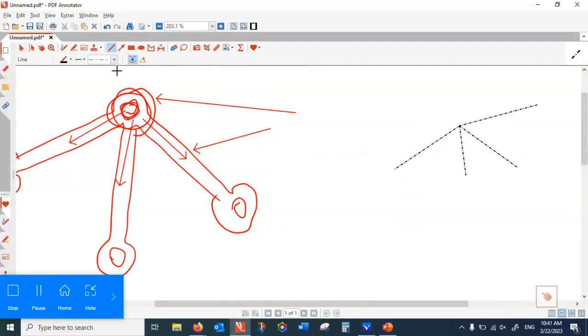So you have one force acting here. This is the force. And then every member you cut, these are going to have either tensile force or compressive, because the member becomes longer or they become shorter. They cannot change their curvature. So sometimes we can anticipate whether the member is tensile or compressive, but in general case, we assume they're tensile.